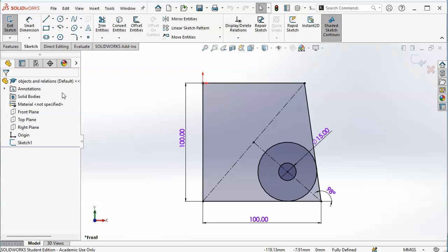So when I click on that, I would say it is not a best practice to save with the sketch open. It will allow it, but there may be some issues with the geometry. Things that you may change, that you may close, might get lost. So, as a best practice, we're going to accept the sketch and then go ahead and complete our save and close the part.